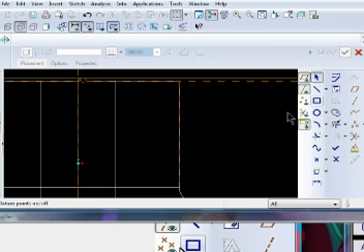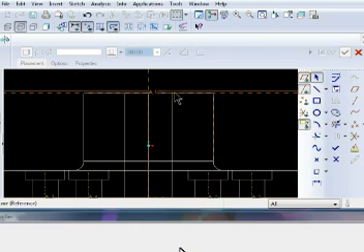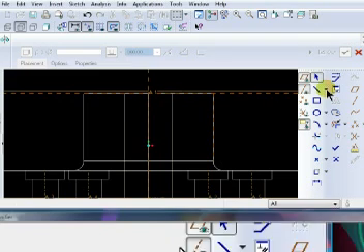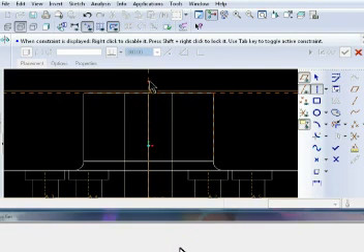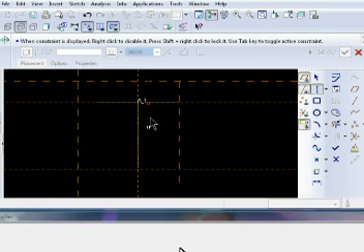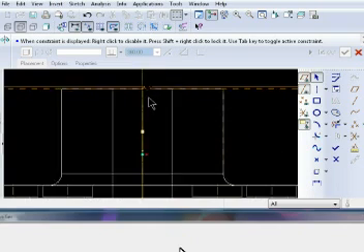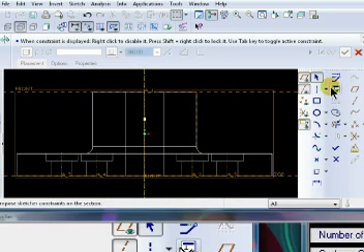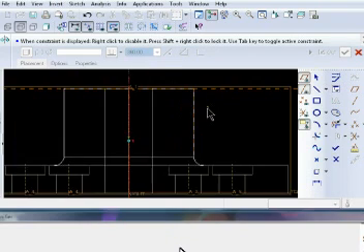Next, now remember this is going to be a revolved feature as well, so we always start with a center line, and the center line is going to be placed right here, and since we referenced the other axis of revolution, it's going to pick it up. And next we will define the cross section of the cut.